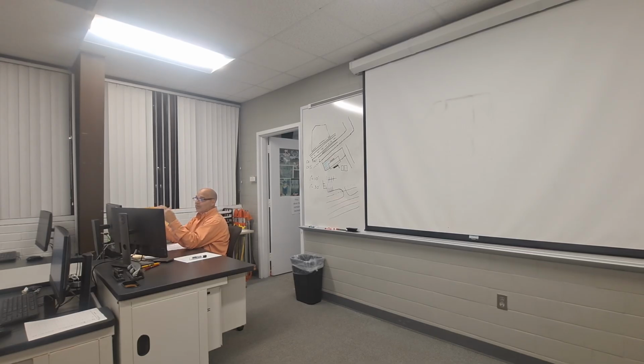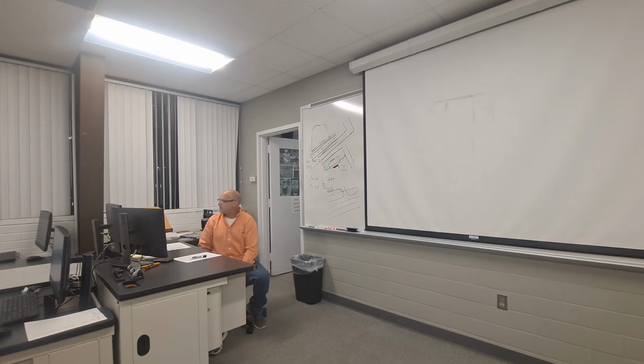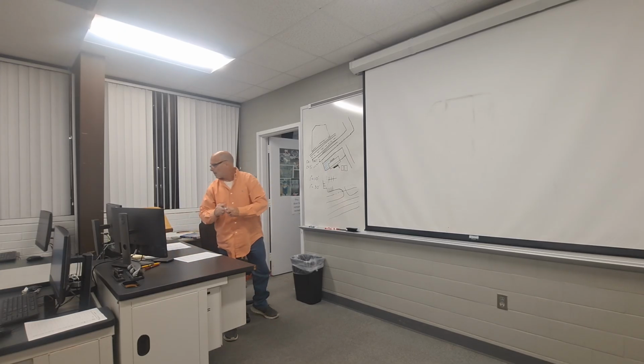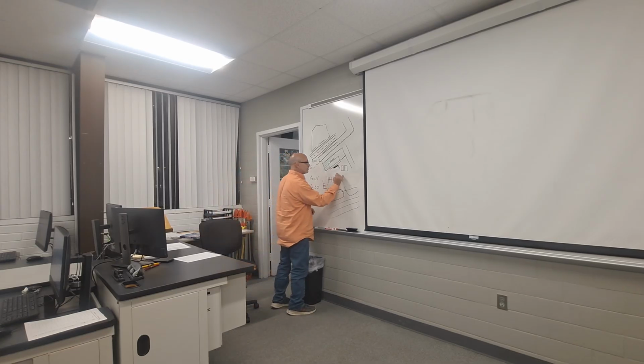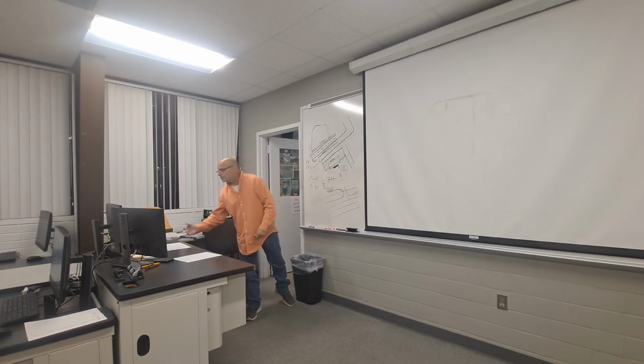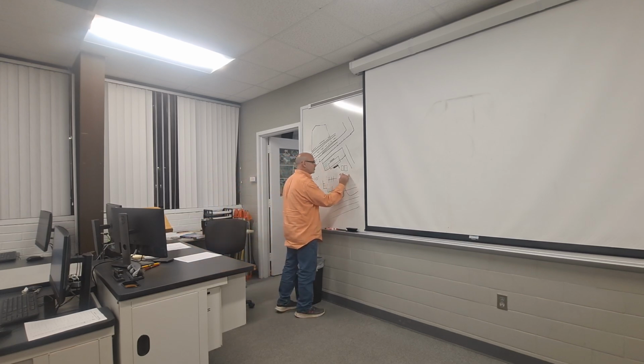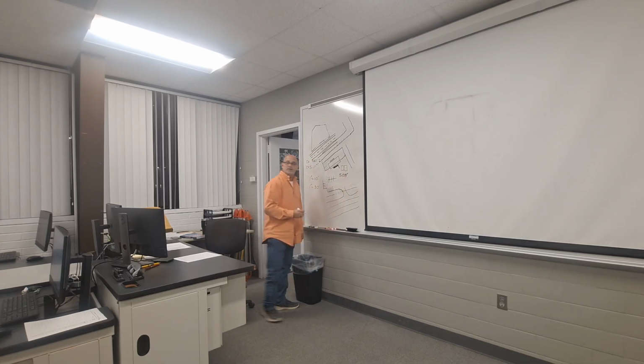So if you're pulling a value from there, you're only going to round it to 2 decimal places. So 410.65 feet, and your direction, your angle for this line, is south 8 degrees, 16 minutes, 18 seconds east. The way we write that, south is just S, because we know we have to start with either N or S, north or south. 8 degrees, when you put it on your drawing, is going to be 08 degrees.